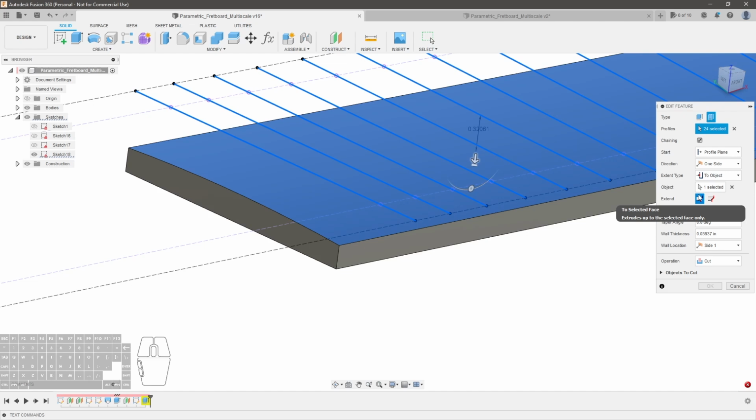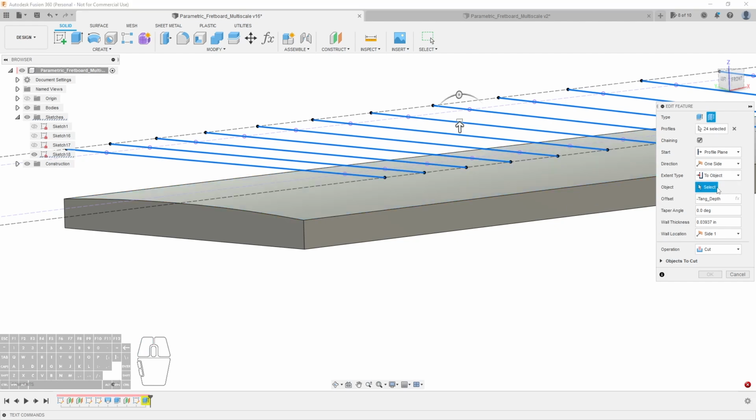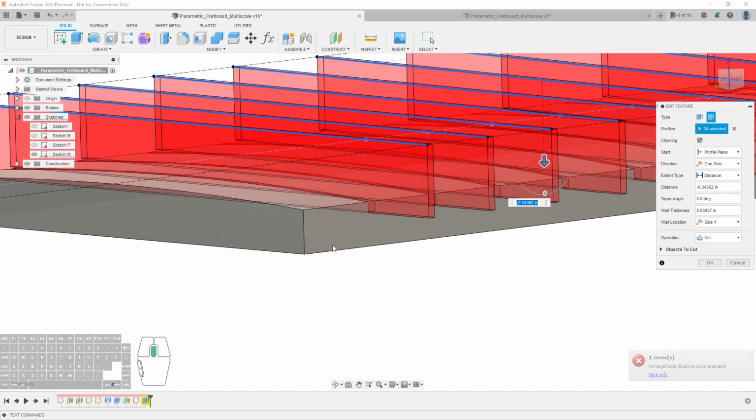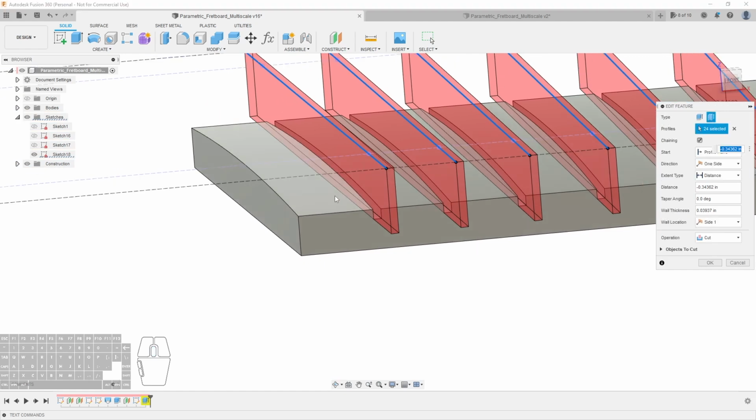I ran into this in my splines are overrated video, where I tried to emboss a splined sketch onto a swept body that had been cut in two different directions. I ended up having to do a flat extrude. So the only extrude type that works for both situations, inside the fretboard boundary or outside the fretboard boundary, is a straight cut. If I drag it down, that means you have a flat fret slot bottom rather than a curved one. That will always work. But when you're referencing the surface, sometimes it will break the sketch on you.